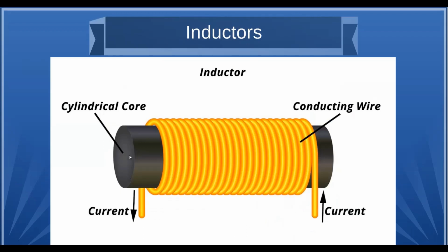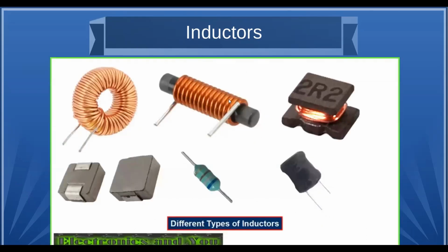And this is a typical solenoid type inductor where you've got some sort of magnetic core. Usually on these, it's like a ferrite rod. There's another picture of an actual one. This is a toroidal inductor where it's ferrite or powdered iron material in the shape of a donut. Now, the reason they've gone to these is there's virtually no magnetic lines of force outside of that donut. Everything's concentrated in the center. And it makes a nice compact inductor.